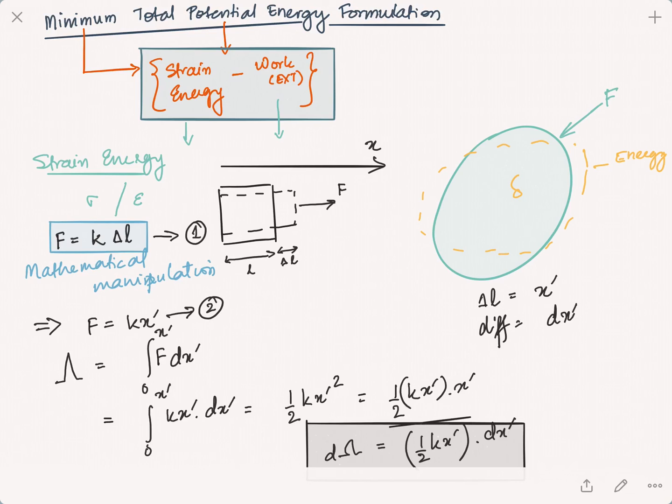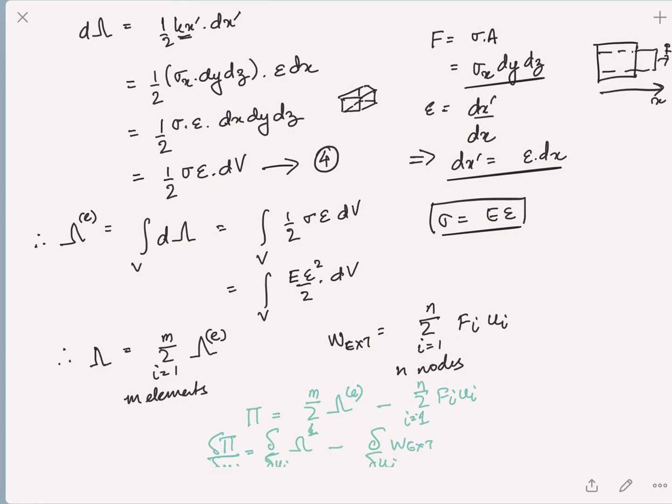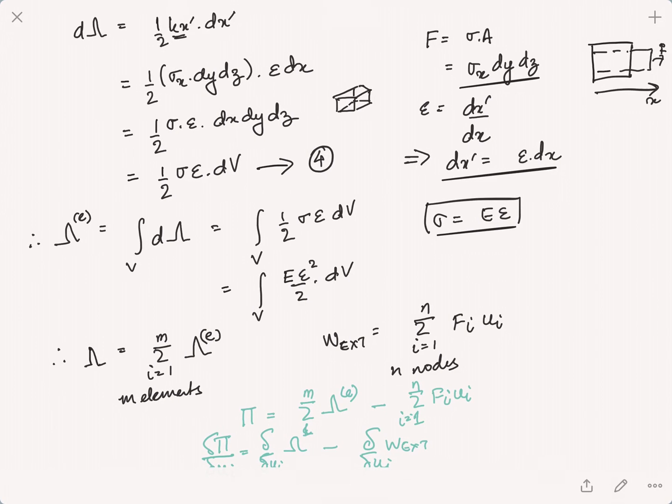And that is basically if you put these minimized equations together, like a list of equations, because it's going to be minimized for a number of displacements, then we will see a set of equations which, when put together, will lead to the equilibrium equation we solve for a linear finite element analysis of any system.